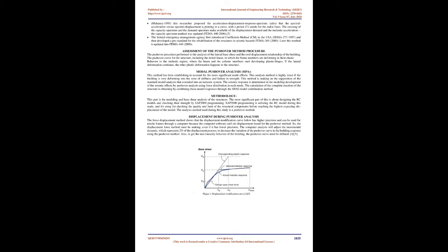Structural elements like columns and beams help the structure resist the loads coming in the vertical direction, and the function of the steel bracing is protection against horizontal lateral loads. The insertion of steel bracing depends on the type of damage to the structure, but commonly steel bracing is put in the openings between the vertical elements. Steel bracing can be internal or external. It depends on the condition of the building.